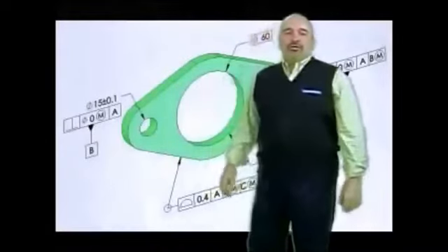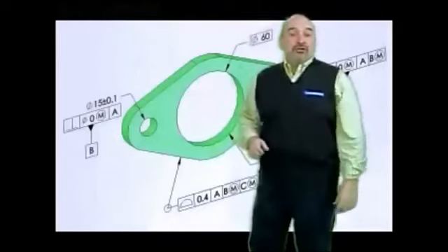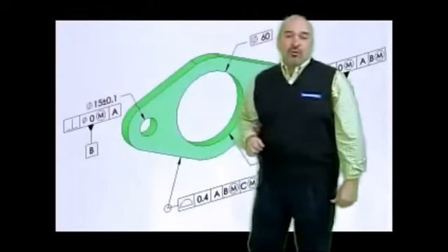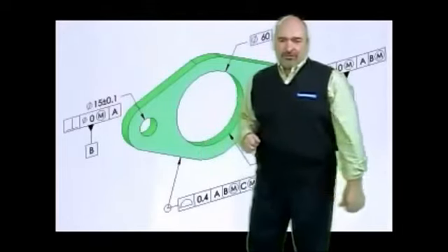I'm often asked if MMC can be used with profile. The answer is sort of. You are not allowed to ever apply MMC to the profile tolerance. You are, however, allowed to modify datum features referenced in the profile tolerance, provided they are features of size.